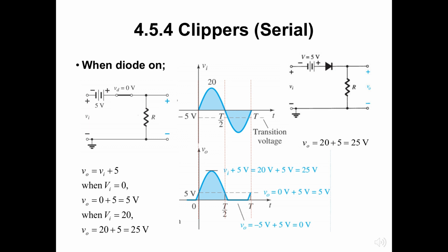The analysis of clipper networks with square wave inputs is actually easier than with sinusoidal inputs because only two levels must be considered. In other words, the network can be analyzed as if it had two DC level inputs with the resulting VO plotted in the proper time frame.